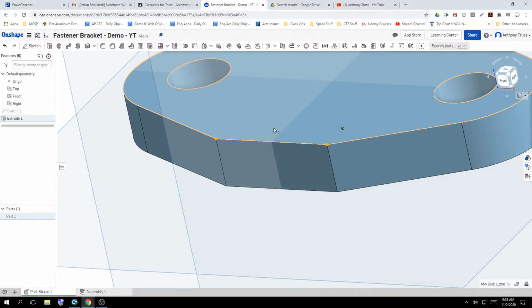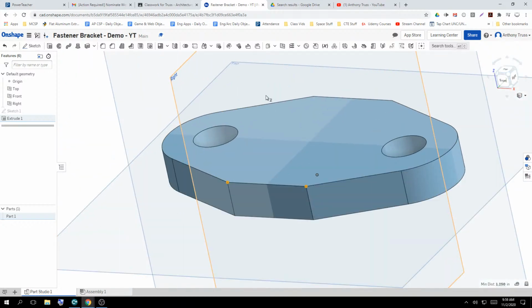The right height is something of an interesting mix, because if you look at the document, the height of the part is referenced from the very bottom to the middle of the circle. Then we still have another 5/8 of material or space to go that's not included. So we really have to take 1 3/8 for the height, subtract 1/2 inch from it, and add 5/8 to it. So we're going to use the expression line in Onshape to put this in so it's easy for us. And I'll obviously put this into the video, and you can just copy along with me if you don't fully get it at this point, because once you see me do it, you will.